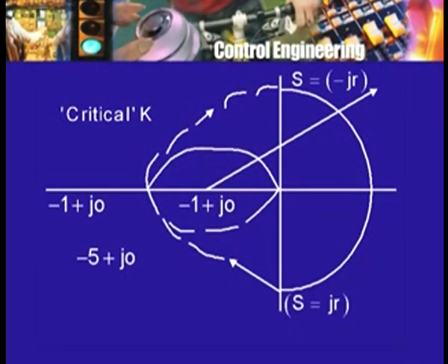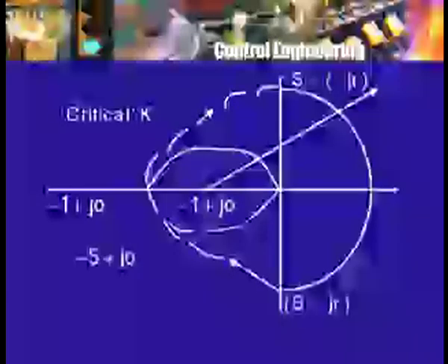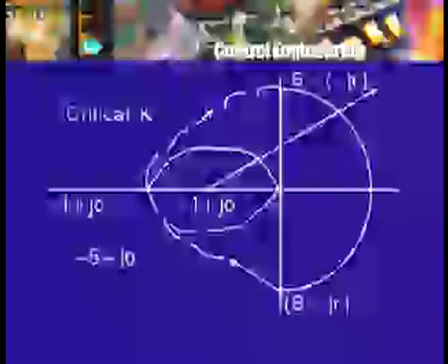Let us say this was the polar plot, the gain has not changed, but the amplifier has introduced a phase shift. For example, the integrator. The ideal integrator has the transfer function 1 by s or k by s. The practical integrator, however, does not have this ideal transfer function. As a result, the practical integrator will produce a phase shift not just of minus 90 degrees, but of a slightly different amount which will change with frequency.